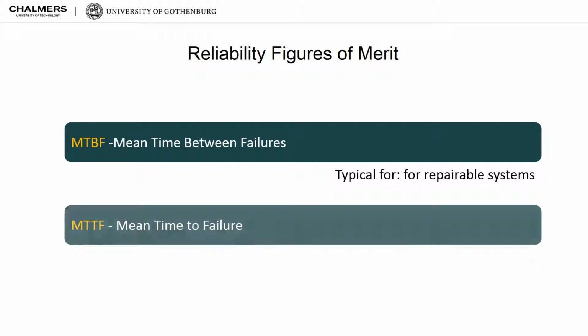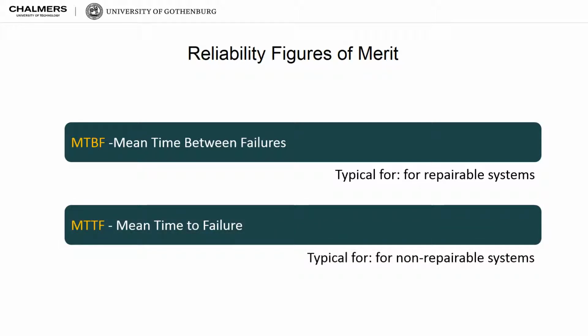Reliability requirements are specified quantitatively using reliability parameters. The most common reliability parameter is the mean time to failure, and this can be specified as the failure rate, and this can be expressed as a frequency or conditional probability density function, or as the number of failures during a given period. Reliability increases as the MTTF increases. The MTTF is usually specified in terms of hours, but can also be used with other units of measurement, such as miles or cycles.